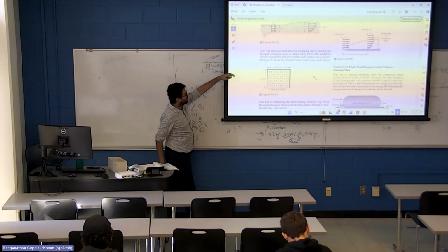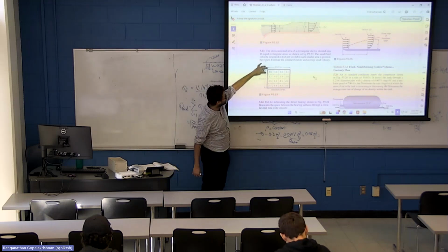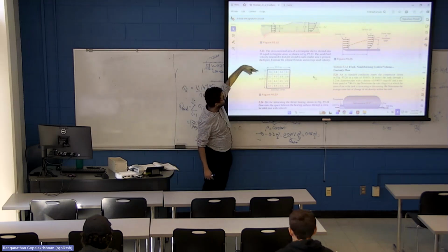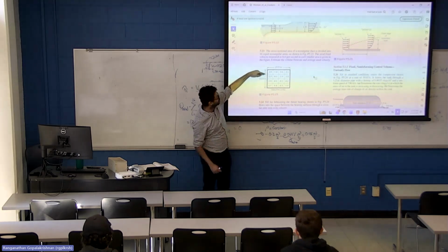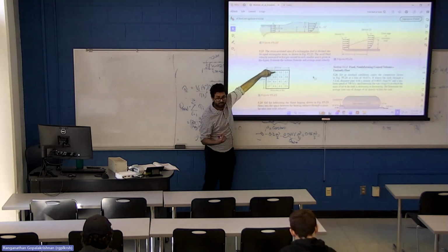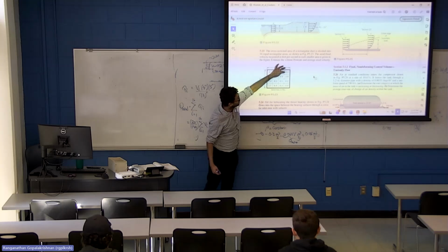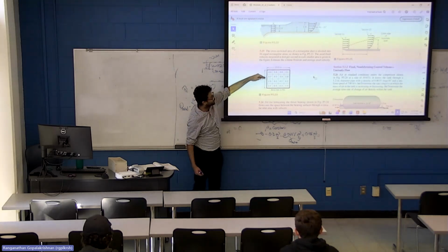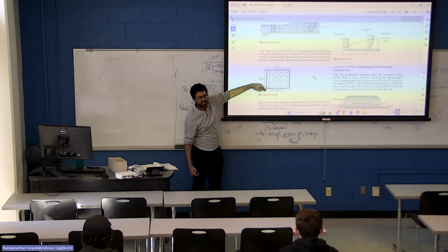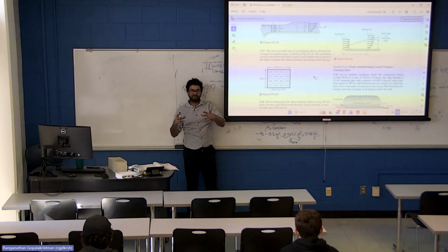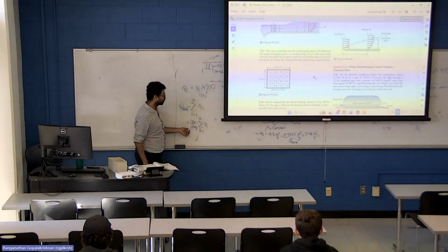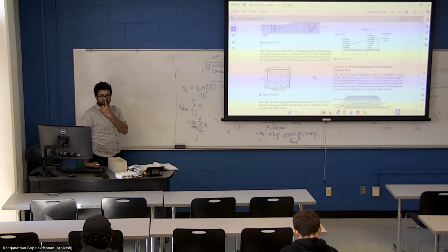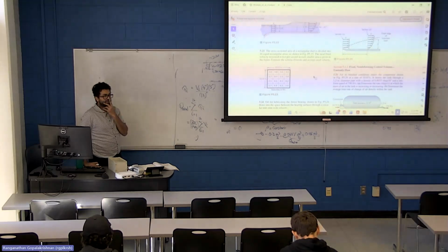The operator would essentially have holes drilled at the walls, insert a probe at the first segment, read out the value, push the probe further, read out the value, push it all the way to the third and fourth, and then move to the next segment, next segment, next segment. This is how practically we will have 16 values. Then you can do the calculation of what's the total flow rate. Are you able to think about this?